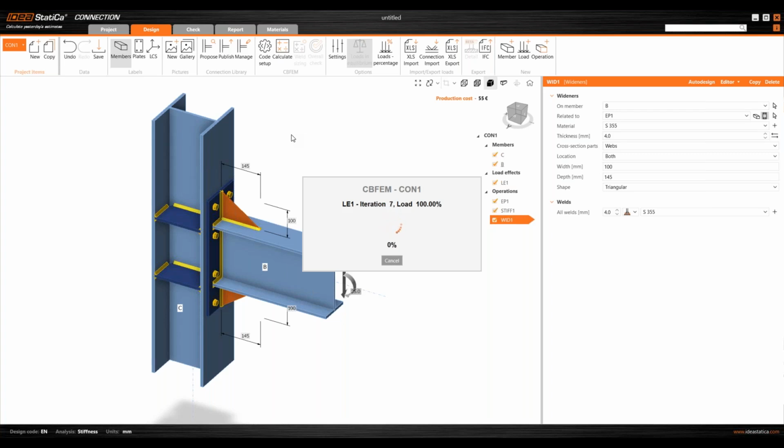So by default, the stress strain analysis also runs in the background. So you will see results, you will see stresses, you will see plastic strain if there is any. And now that's when the application applies the loads for the stiffness analysis divided into those initial 12 steps I was talking about.